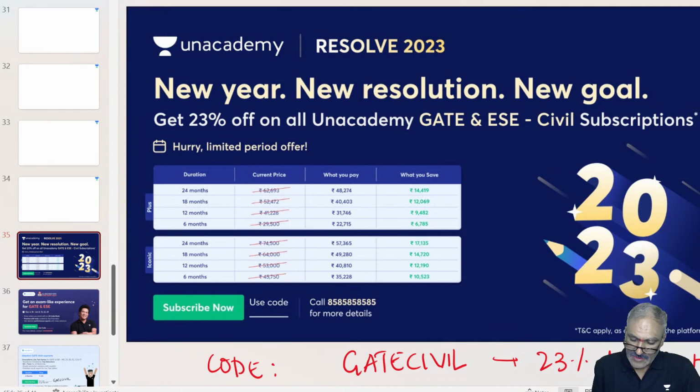Because we could not cover frequency analysis in the last class, as we solved so many questions on mean precipitation, which is very, very important, especially the Thiessen polygon method. So we covered a decent number of examples related to the Thiessen polygon method. Now, one more important topic related to precipitation is frequency analysis of rainfall data.